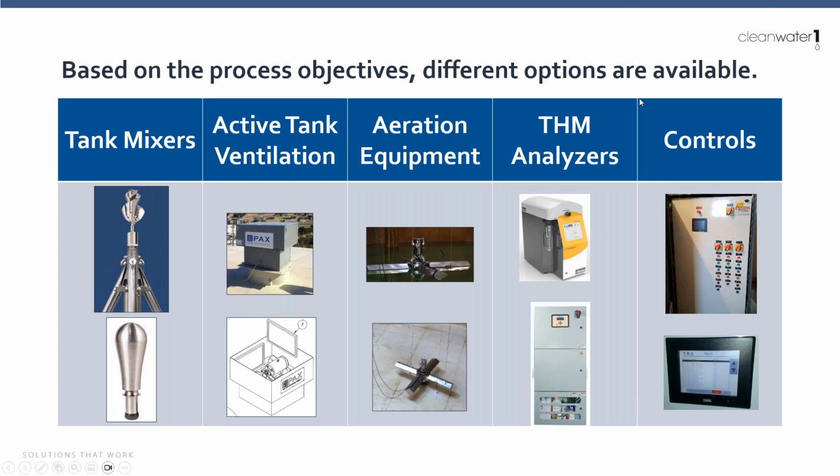And then we integrate these all with integrated control panels. If you think about it, these are all just motors. We've got motors spinning on the roof for the ventilation system, motors spinning with the mixers. So by having a single integrated control panel with an HMI, we don't burn a ton of SCADA channels monitoring each of these remotely. We can just have a run, off, fault, and then if there's a problem with an individual piece of equipment, you can go to your local PLC at the control panel to diagnose it.